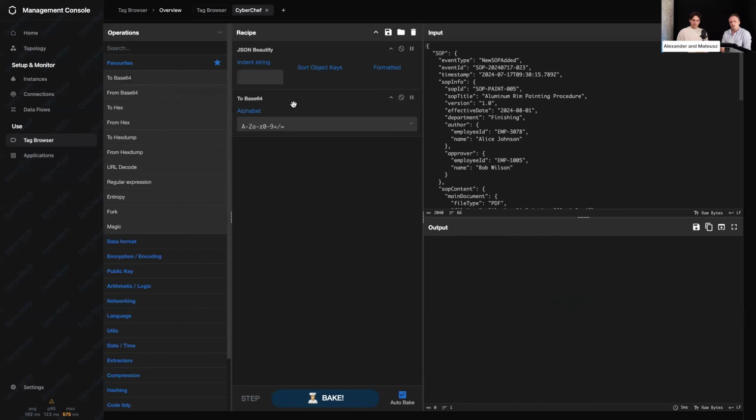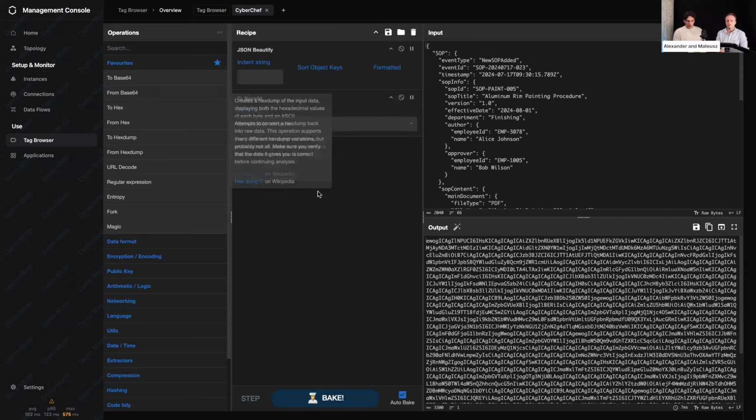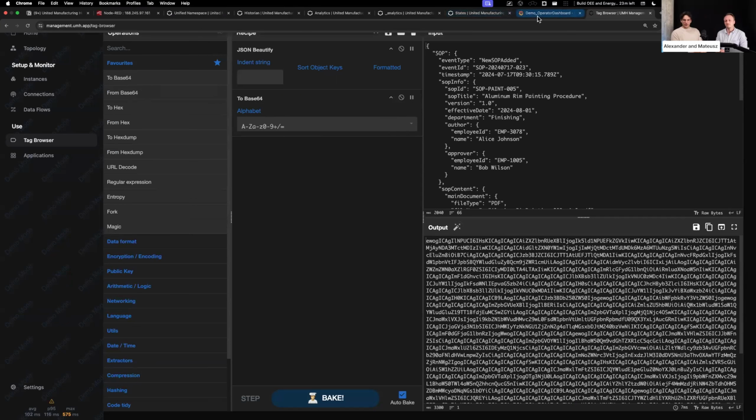And you pretty much just drag and drop stuff over here, get immediately an output, which is very cool if you get something from a Modbus server or something. Yeah, like something randomly encoded in base64 or like a bit array or whatever. Take it there, understand it, and then do the functions that help you bring it into an understandable state, back to the protocol converter or into the stream processor of Benthos, and then have only nice data in the tech browser as a resulting step. So a little bit of DataOps, as some people call it, data understanding, data manipulation, easy at your disposal.